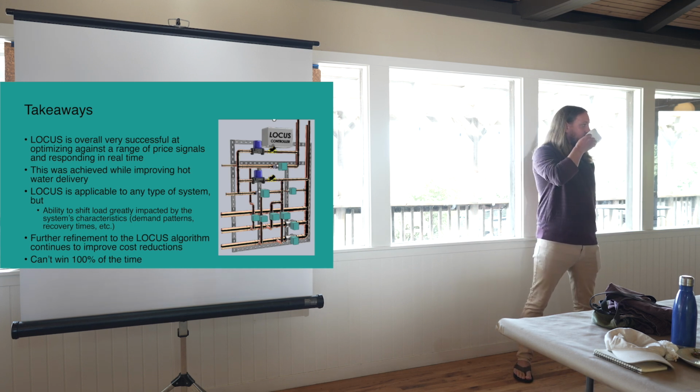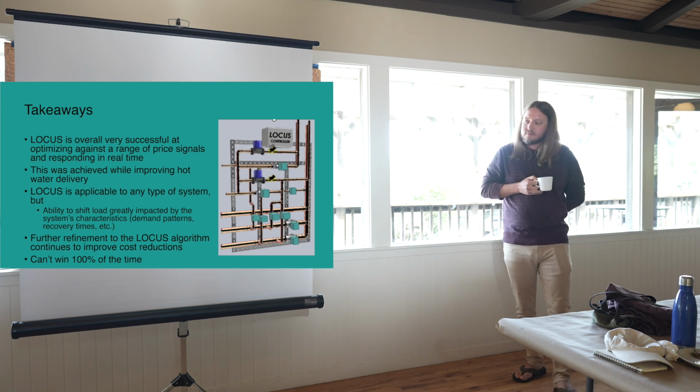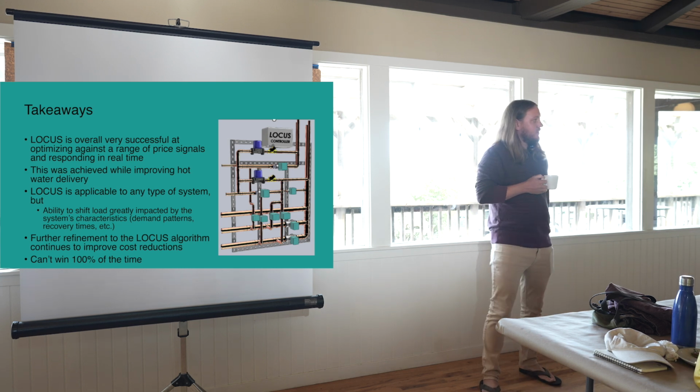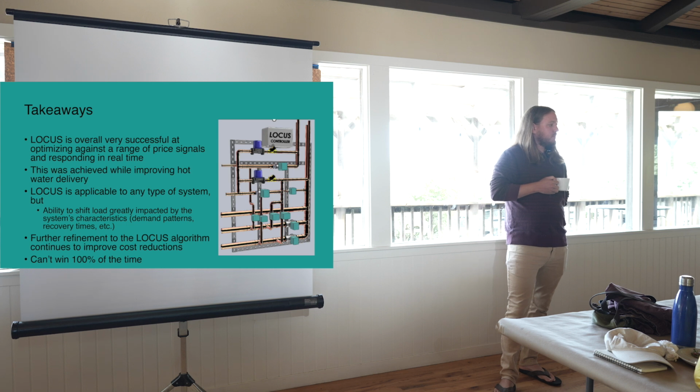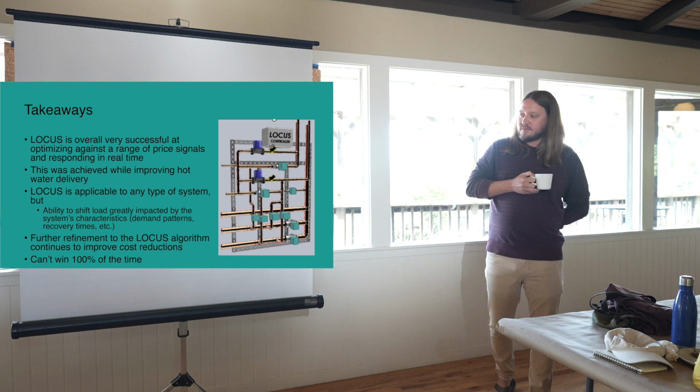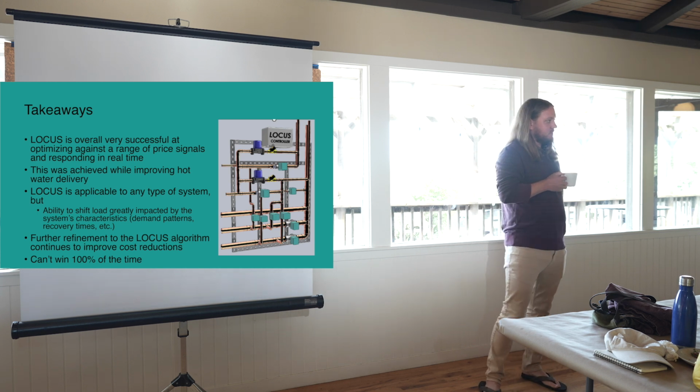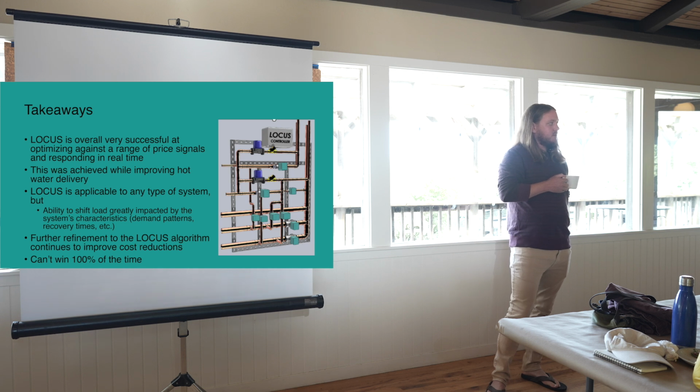So I did have one slide with multiple sensors and just one large tank. And so I think Locus's intelligence could be applied to that really well. I think there are fewer applications in terms of integrated heaters and recirc management that make that single tank more difficult. But for split systems in general, especially at the commercial scale, I think that's a really good solution to eliminate pumps and valves. But this will spread to a wider array of applications. And if you're retrofitting and you don't have the storage, if you don't have storage with 3 or 4 thermal wells, tank manufacturers don't tend to put those in.